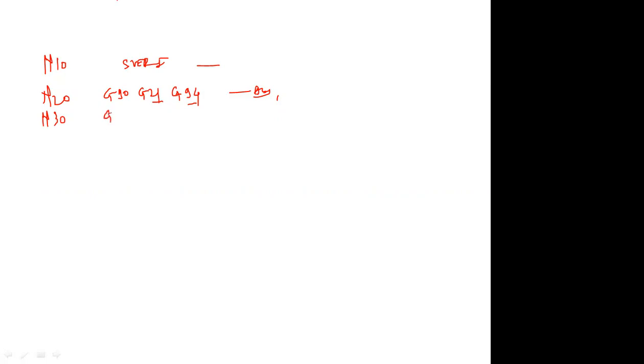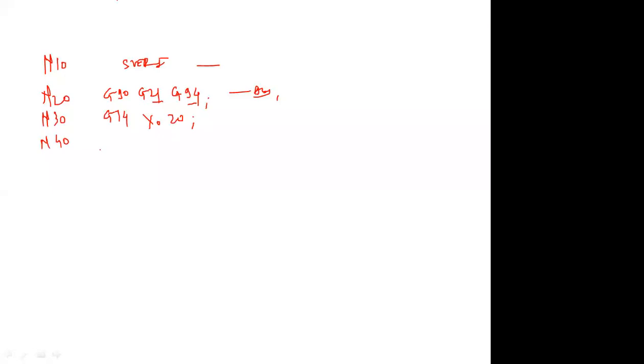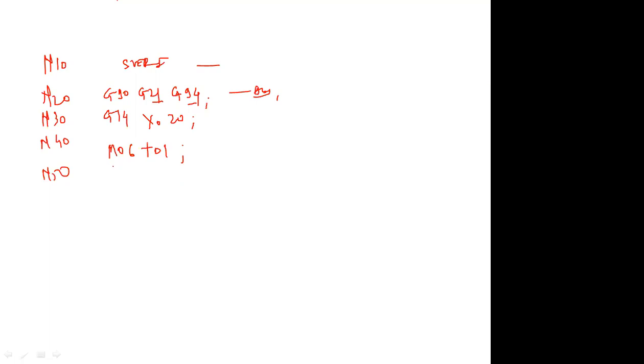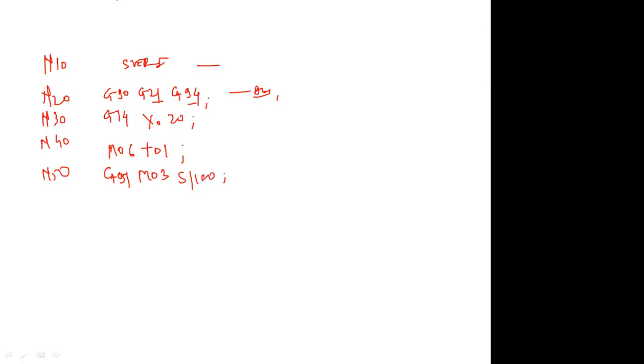G74, X0, Z0. Okay, reference X0, Z0. Next N40: M06, T01. Next N50: G97, M03, 1100. Next: M08.